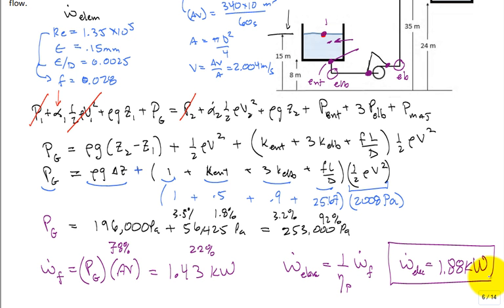Yes, sir. When you say negligible minor losses, I know it's contractions, expansions, elbows, entrances, exits. Right. Now, when it says negligible head loss... We use head loss and pressure loss almost interchangeably, because head loss is just pressure loss divided by rho g, and you take it out of your Bernoulli equation.